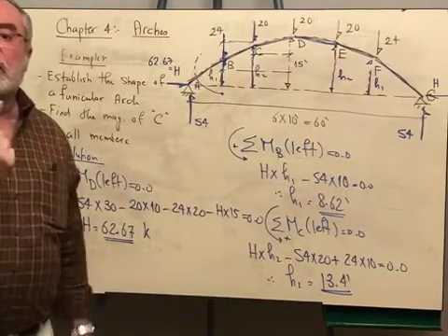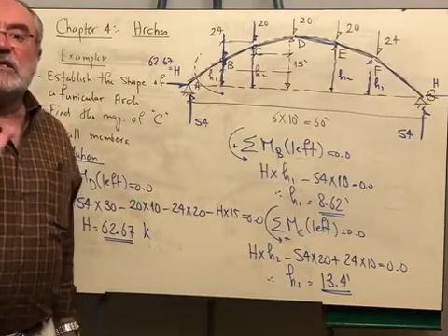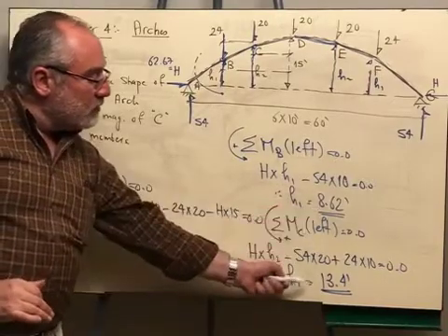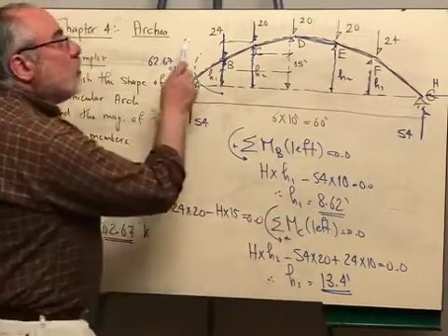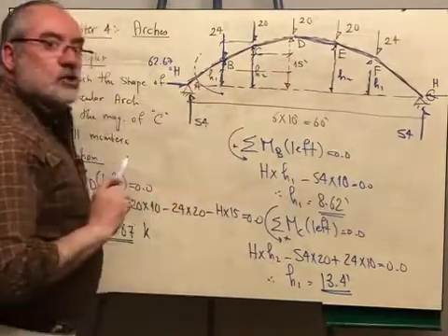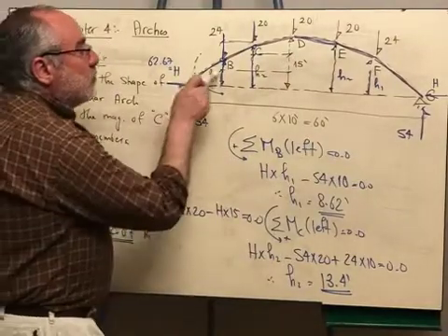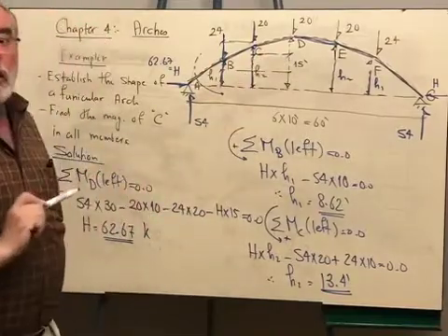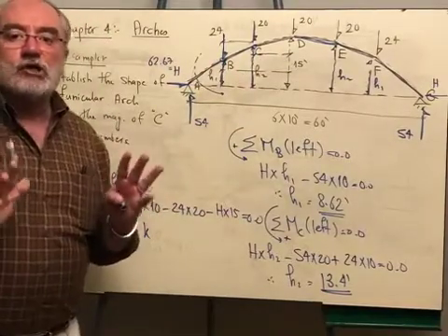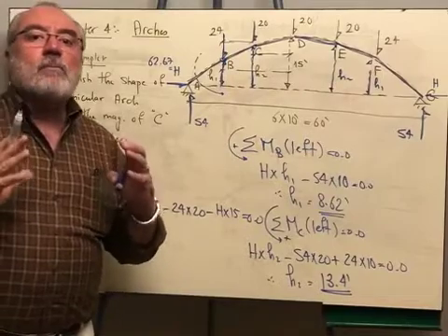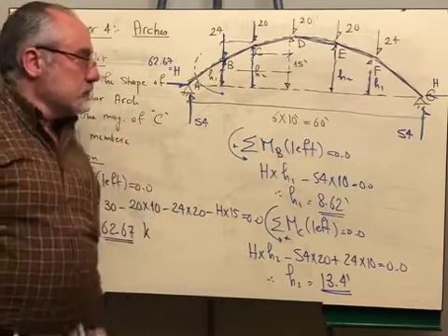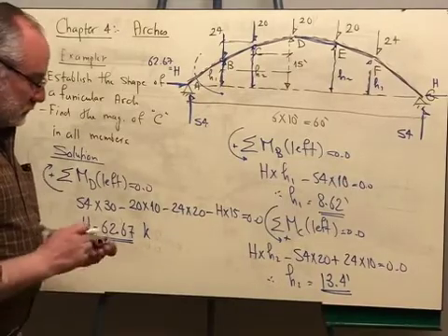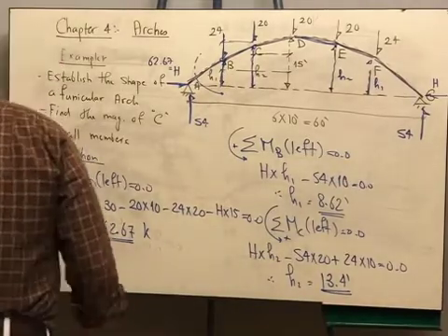There is only one geometry that will satisfy the condition of being a funicular arch, and we calculated this value and this value exactly. If any of these loads was changed, or if any of these rises was changed, then this is no longer a funicular arch. The funicular arch is funicular for only one particular load case. If I want to get the compression that will develop here, what do I do?